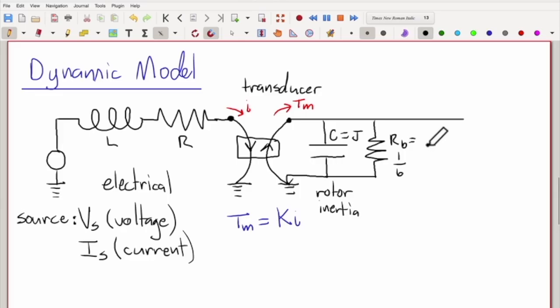This is one of the differing conventions for how different domains usually label things. And the last one is a pure source, which I'm going to draw like this, a torque source. I'm going to call this TC. This is a velocity dependent drag, and this is a Coulomb drag, TC, which is also due to bearings and or brushes, that does not depend on RPM. So over here is the coil. Here's the coil. And over here, I'll just call this drag.